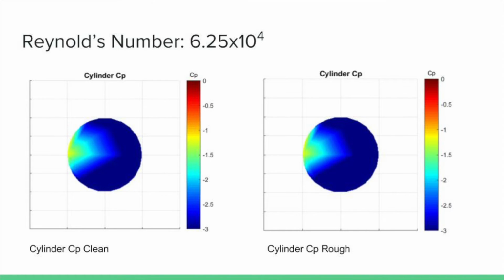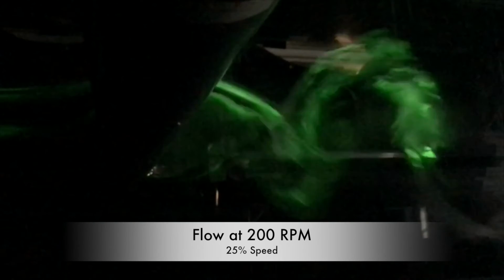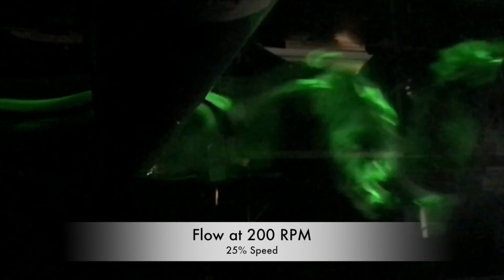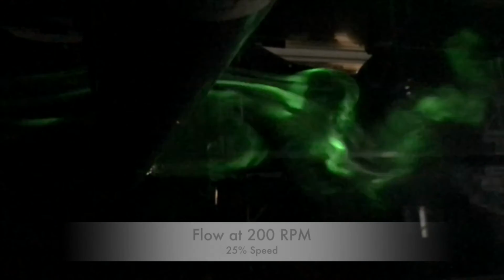Again, due to the lack of difference between the two graphs, we are unsure if the boundary layer was tripped. This plot of the CP graph again shows the similarity of rough and clean runs. Vortex shedding frequency for this Reynolds number is 16 Hz. It is important to note that the frequency increased from the previous run. This is because the vortex shedding frequency is directly related to the value of the free stream velocity.